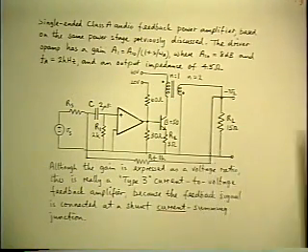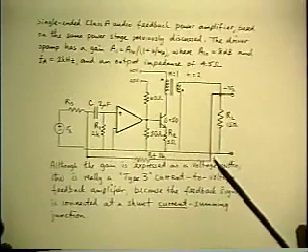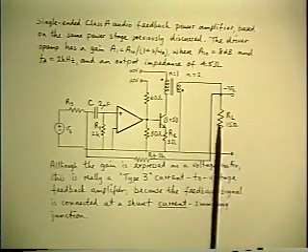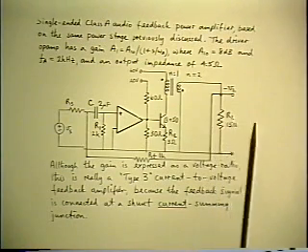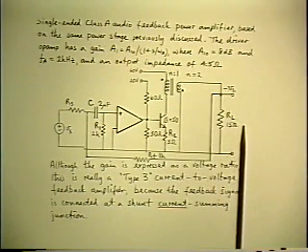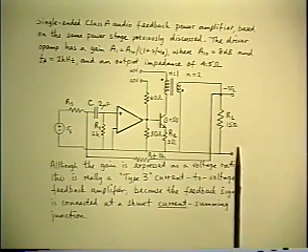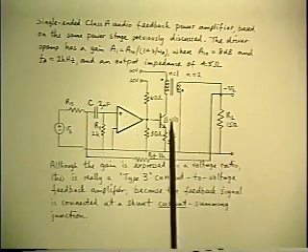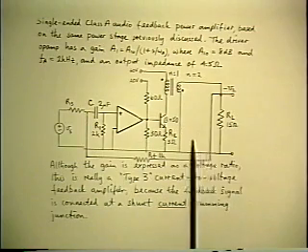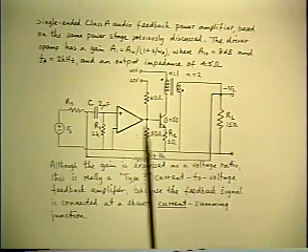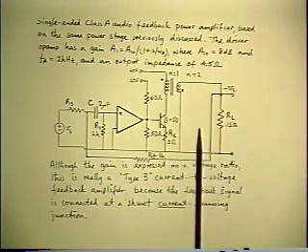Okay, let's calculate now the inside output impedance. Inside output impedance is the only one that matters in this case. Outside output impedance is of no interest because nothing else is going to be connected beyond the loudspeaker. So usually the audio amplifier is specified separately from its load, so it's the inside output impedance that would appear on the data sheet.